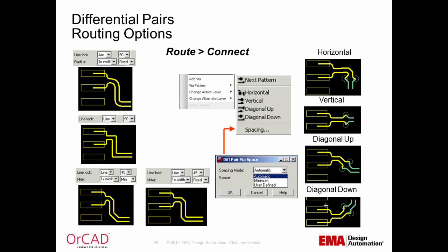There are two routing styles for differential pairs, edge to edge on the same layer or tandem on adjacent layers. To route tandem styles, you must first seed the routing by starting the routes on the signal layer in single trace mode on the desired layers. Then you can pick up the pair and continue routing.